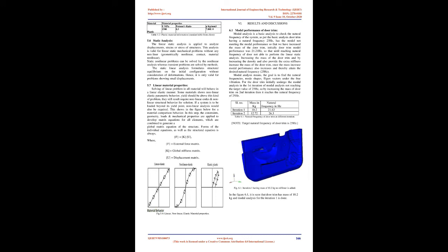Engine at 1000 rpm and load at idle. Harmonic analysis is performed with and without the stiffener for the automotive car door. In the harmonic analysis, displacements were obtained for both conditions. With the stiffener, displacements were less, giving a safe design.